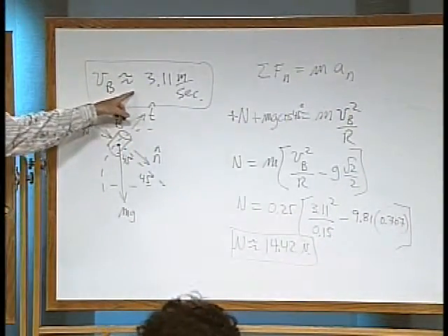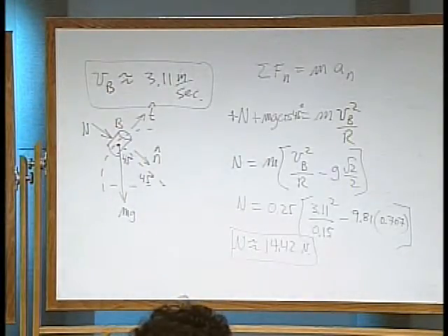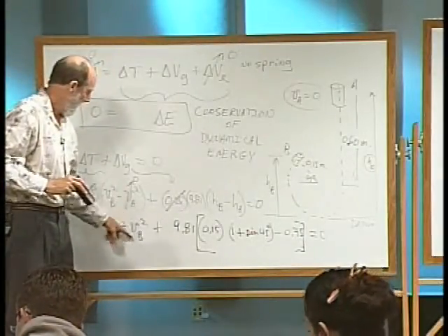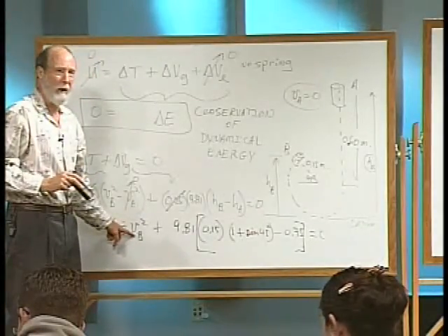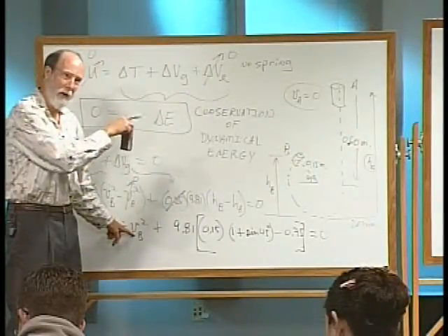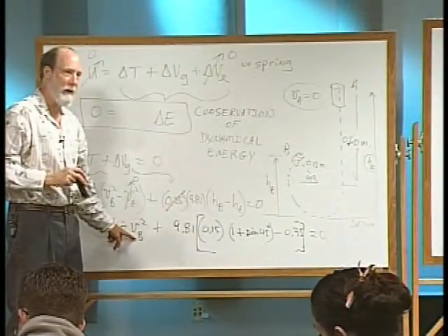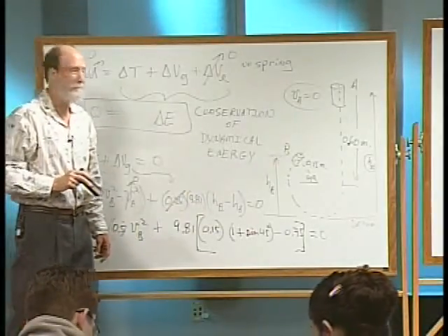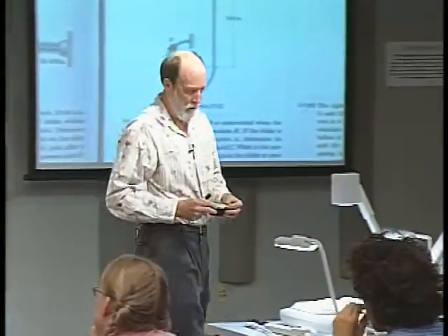What you're going to see in quite a few problems is that when you're doing the energy, your kinetic energy terms, and you're finding velocities, I would suggest you write down what the square of your velocity value is, because you're going to see that show up frequently in cases like we see here, because you're looking for that normal acceleration, which involves the square of the velocity. So just jotting that value down will save you having to do an extra calculation. Okay? So that's how you do these.